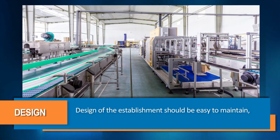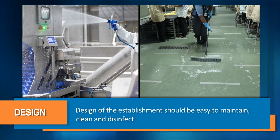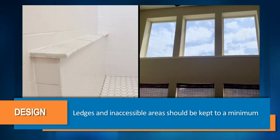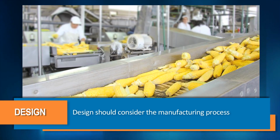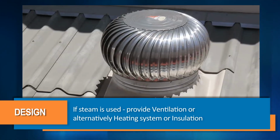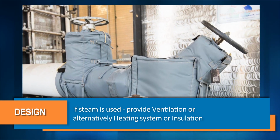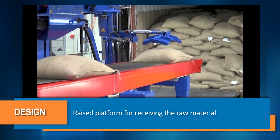The design of the establishment should be simple and easy to maintain, clean, and disinfect. It shall provide sufficient protection from environmental contamination. Ledges and inaccessible areas should be kept to a minimum. The design shall take into consideration the manufacturing process. For example, if steam is used in the process, ventilation shall be provided, or alternatively, a heating system or insulation may be designed to prevent condensation. There should be a raised platform for receiving the raw material.